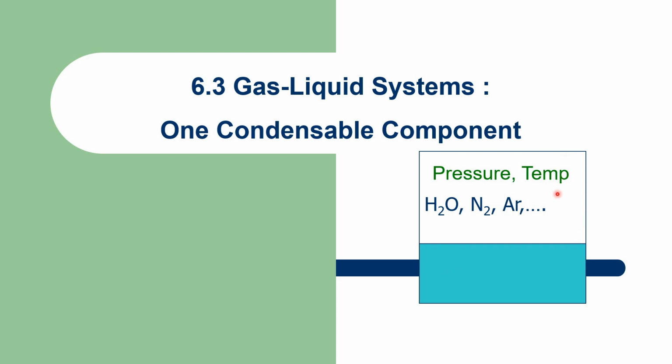If the temperature is high, the H2O tends to become vapor. How about the pressure? If you want to make the H2O condense, do you want to use high pressure or low pressure? High pressure, right? So temperature will be decreased, pressure will be increased in order to condense H2O. In this case, H2O will be condensed first.